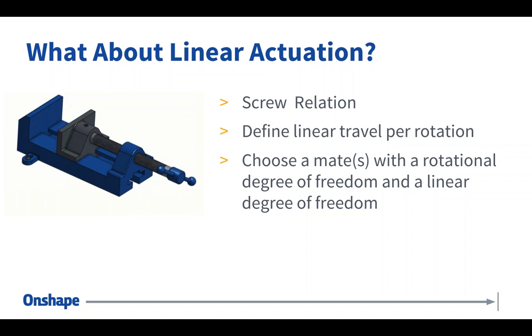Question. If the ratio is wrong, can Onshape identify it tooth to tooth? The answer is no, you cannot identify. It's not going to recognize the two are overlapping or clashing, so to speak. So you would need to know the ratio and input that. Now, you'd be able to see it pretty obviously, but it's not going to automatically correct itself, so to speak.